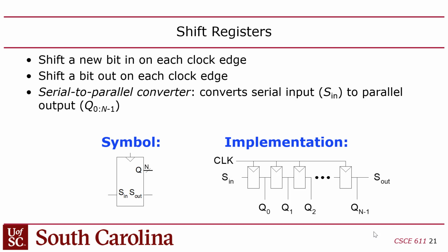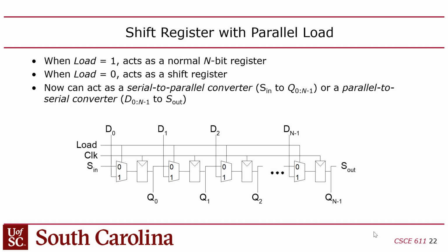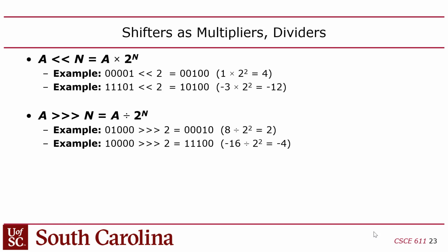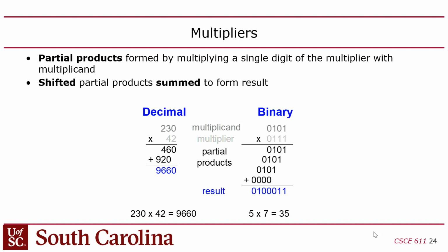But shift registers are used a lot to create delay lines, and also, in this case, you can create a parallel-to-serial converter. You can load in data in parallel and then shift it out in serial, right? So this is what happens with your HDMI connection, SATA connection, like when you plug your monitor in. The CPU sends pixels to the monitor in parallel, and they're shifted out in the HDMI cable. It's one bit at a time, right? Same thing with SATA. That's for hard drives, disks. That's a serial protocol. So anytime you have to do a parallel-to-serial conversion, use a circuit like this.